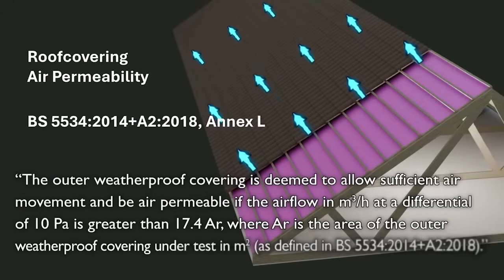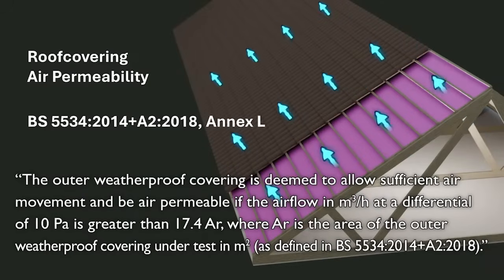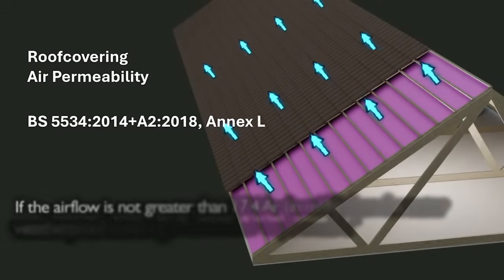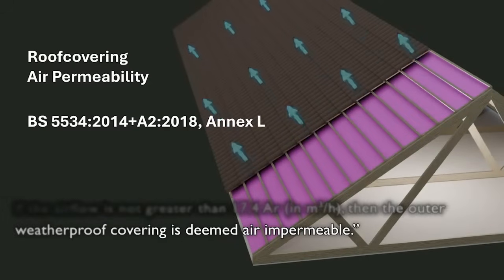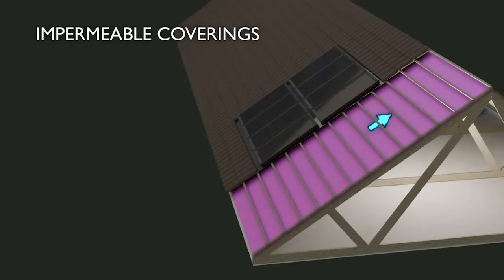The outer weatherproof covering is deemed to allow sufficient air movement and be air permeable if the airflow in metres cubed per hour at a differential of 10 Pa is greater than 17.4 AR, where AR is the area of the outer weatherproof covering under test in metres squared, as defined in 5534 2014 and A2 2018. If the airflow is not greater than 17.4 AR in metres cubed per hour, then the outer weatherproof covering is deemed air impermeable. If it's not permeable, then some degree of ventilation will be required.